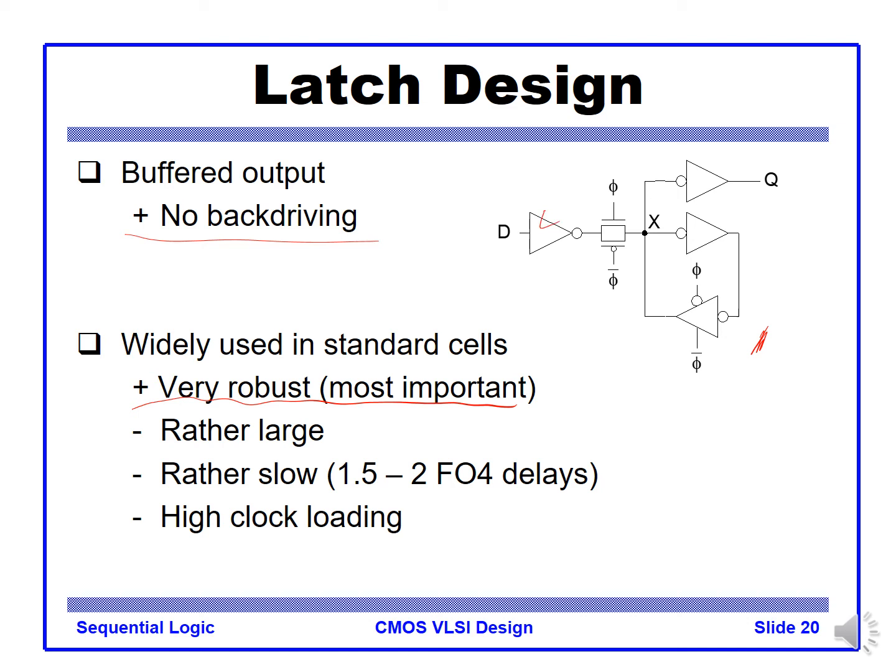But we have many devices, inverters and flip-flops. This is a single latch implementation. To reduce the output loading effect, you may add a buffer like that, adding another inverter there, but then you get the inverted output, right?